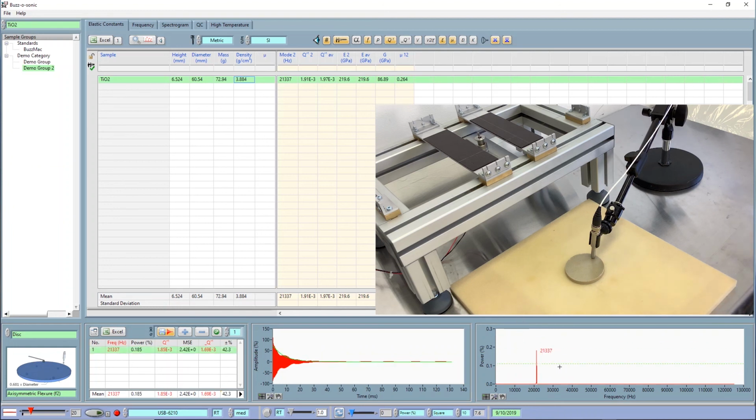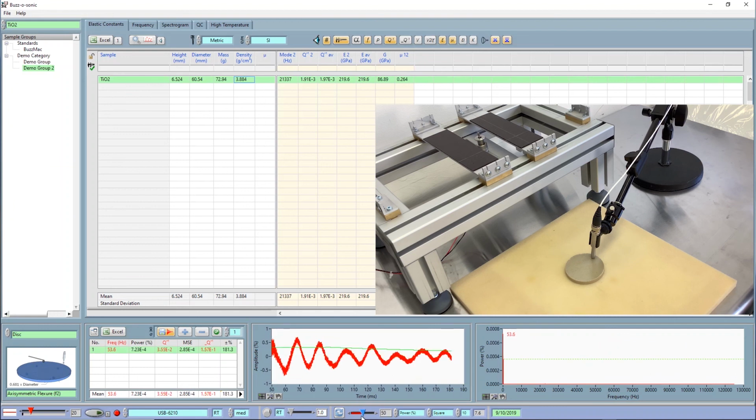If you've got the threshold slider too high up, you can right click and say center threshold. This of course you can offset like we showed you before, but if you want to reset it, just click that.